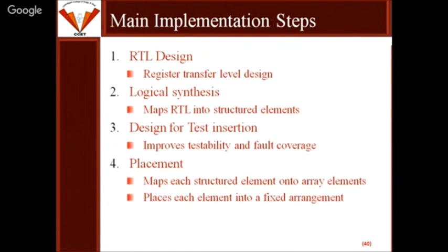So the main implementation steps are, first of all, we go for the RTL design, register transfer level design. Then we go for the logical synthesis. It means it maps RTL into the structured element. Then we go for the test insertion. It means we improve testability and fault coverage will be there. And at last we go for the placement. So it maps each structure element onto the array elements and places each element into the fixed arrangement depending upon the requirement.